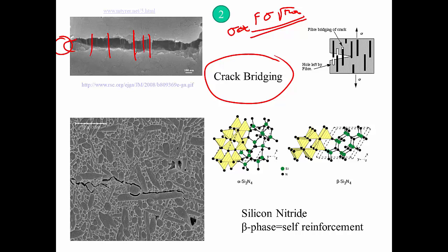And the way that this is done is either you have a fiber that essentially connects the two sides and it is still intact, that is, it's connected to both sides, so you have something like this, and this fiber is still attached at least further into the surface to the matrix, and this anchoring, if you wish, reduces the stress at the crack tip. Or if you have a process during which these fibers are cut, okay, you lose the support.